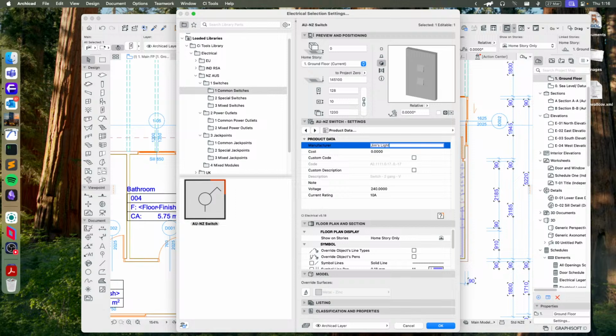Moving along to the other end, this hotspot here controls the corner angle. So at the moment, we don't have anything showing. So if we have it set to 180, which it is now, it's not doing anything. But if we move this out until it has an actual corner that it could draw, you can see the preview is showing me the next edge that it's going to add going around a corner there.